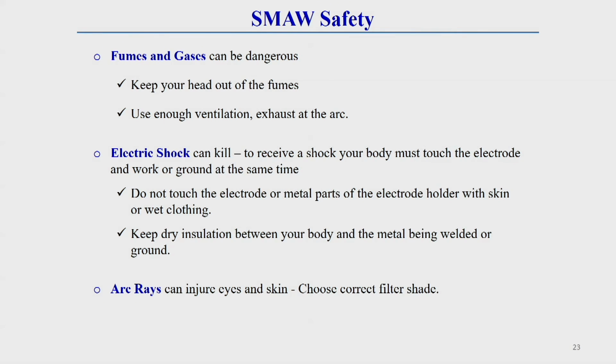So here also in this welding operation there are some safety precautions that you should keep in mind. Generally in this welding process you observe that fumes and gases are generated. These fumes and gases can be harmful to the welder or whoever does the welding. That is why always keep your head out of the fumes, and use enough ventilation and exhaust at the arc. Nowadays for doing this welding operation in a shop, generally an extraction system is used which extracts that fume and other things. So there is less chance of effect on the welder.